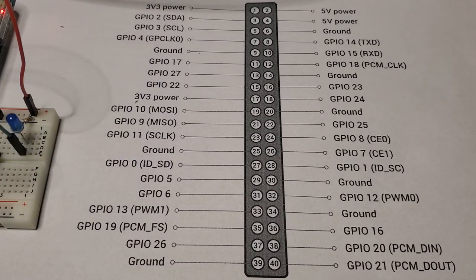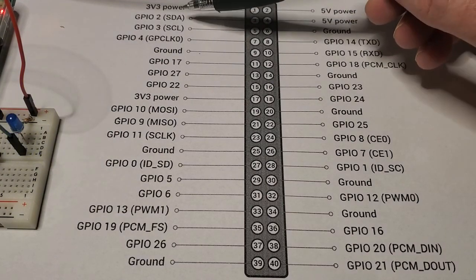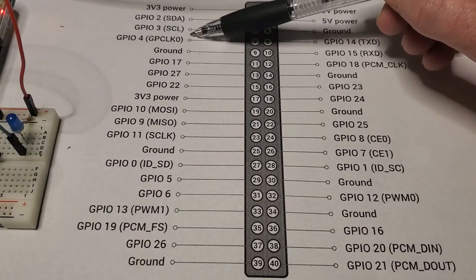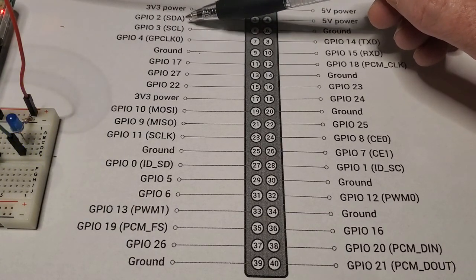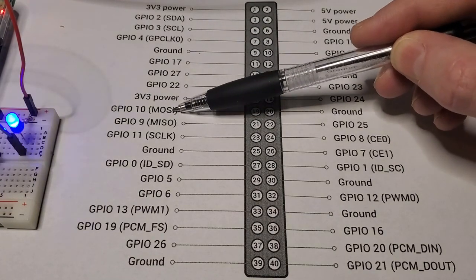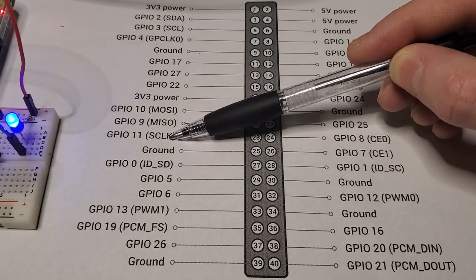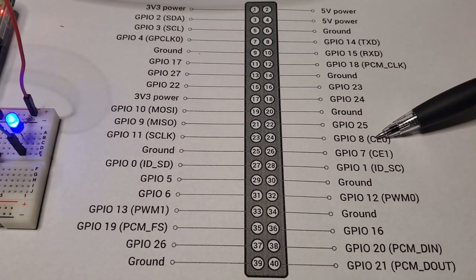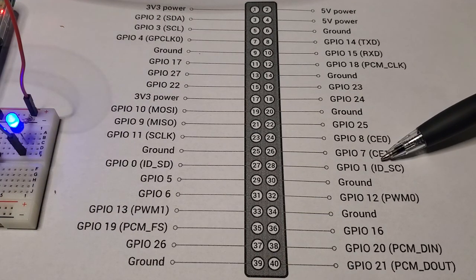Let's walk through some of the special purpose ones. You can see up the top here, we've got SDA and SCL. These are the I2C pins. You can also do SPI programming. So here's the MOSI, MISO, the clock, and the chip select pin, and you've got 2 available here.